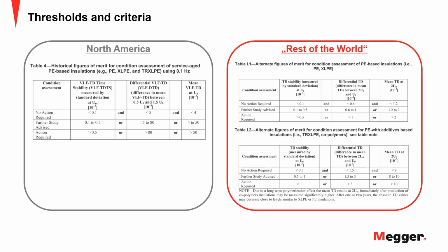which methods you run. And I want to mention one other test that we didn't talk about here. If you really want to do a complete assessment of a cable, you should also probably perform a sheath test. Because if the sheath is jeopardized or compromised, it's just a question of time till the insulation gets compromised. It's not very typical in the North American market, but other markets, when they do a condition assessment of a cable, even on medium voltage cable, will also do a sheath test.